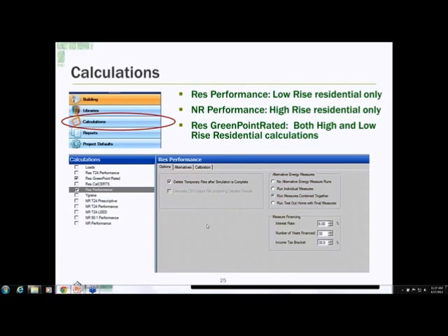In actuality, I haven't really had the need to use interior partitions when I'm doing any energy compliance for Title 24, and I haven't had any plan checkers ask me to include that in the model simulation. So they only wanted to see exterior walls, not partitions.